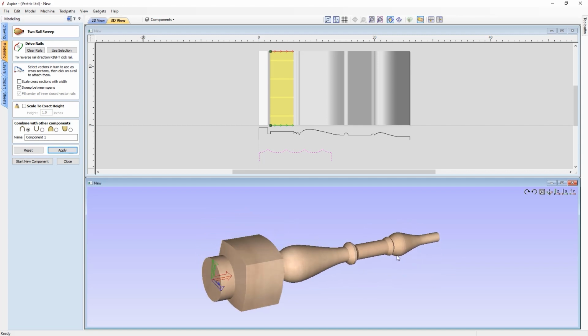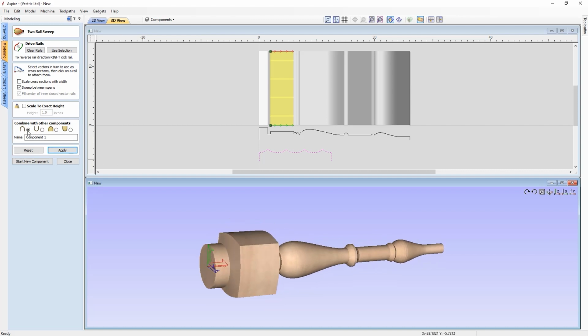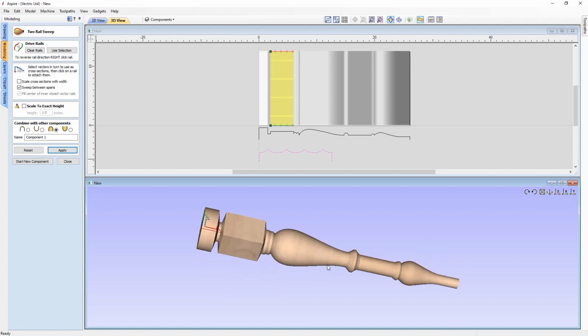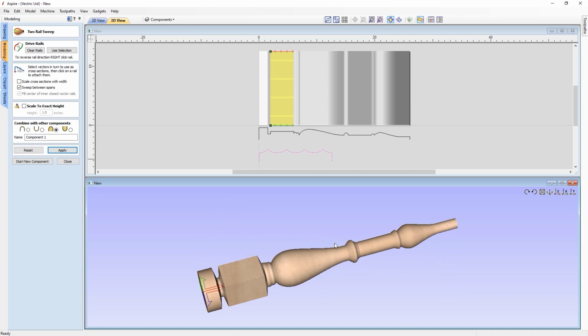So we've got quite a large shape there, and the reason for that is because it's currently adding on top of our current composite model. So we're just going to go ahead and set the combine mode of that to merge, and we can see now it's blending in, and we've got that box shape there, and it's looking pretty good.